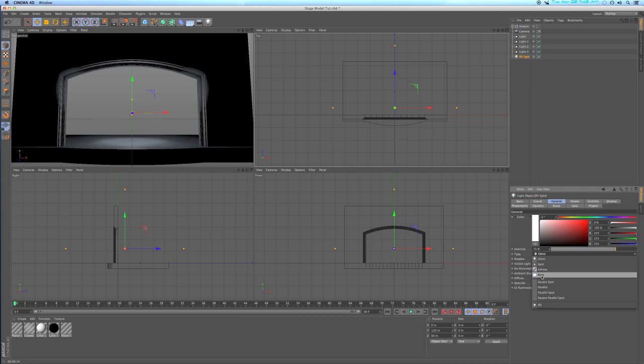If you had a window in your set and it was say a 2 foot by 2 foot window that had frosted glass in it, you might want to set an area light for that and make it 2 foot by 2 foot, and it would create a very soft light coming in that window, and the shadows would be very diffused. But for the most part in our scenic modeling, we're going to use Omni lights and spotlights. I can also set the shadows here, but for the fill light, I'm not going to do any shadows because it just increases the rendering time, and I don't really need those shadows. I've got shadows from the other lights.